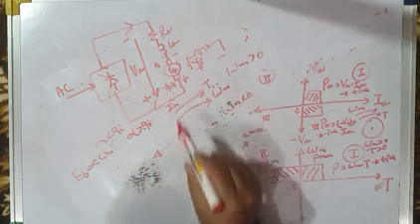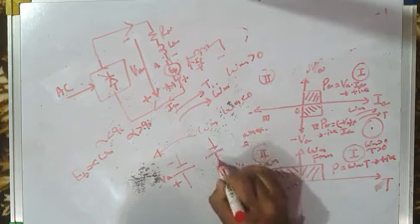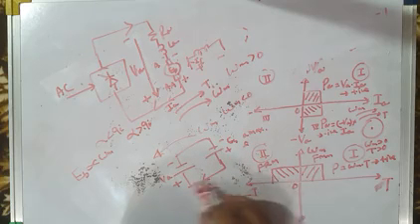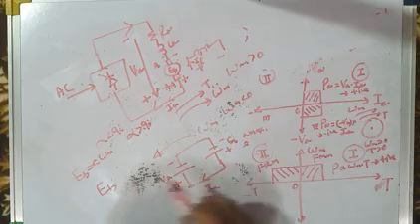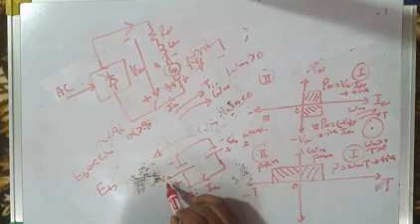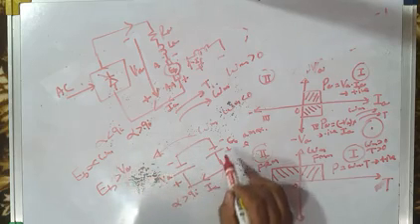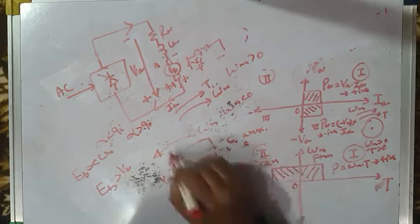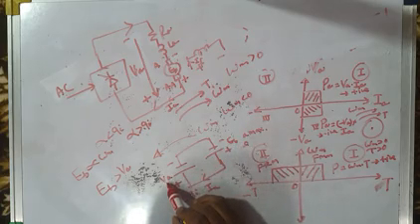so that the average output voltage becomes negative, like this. Now again, it's this type of situation. This is the average output voltage and this is the back EMF. Back EMF has reversed its polarity due to speed reversal. To limit the magnitude of current, EB should be greater than VA. You have to make alpha greater than 90 degrees, but in such a way that the average output voltage is less than EB. So EB is slightly greater than VA. It should not be much greater than VA, because if EB is greater than VA by a larger amount, it will result in huge current that may burn the armature winding. So EB has to be greater than VA, but by a small amount, maybe 2 to 3 or 5%.